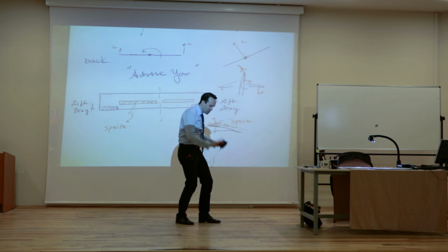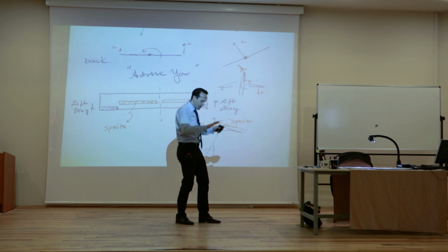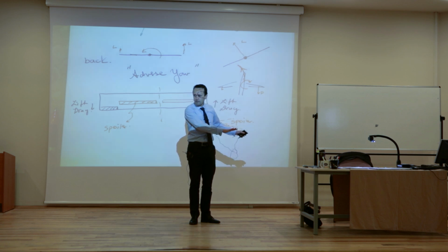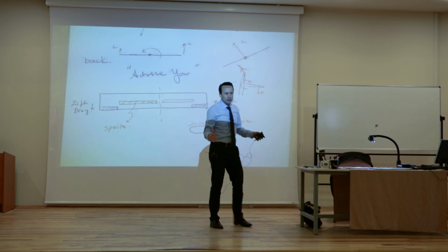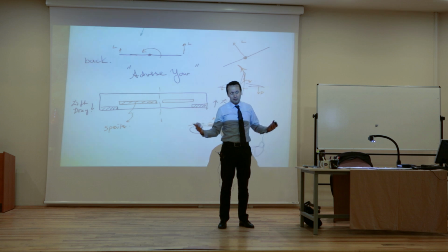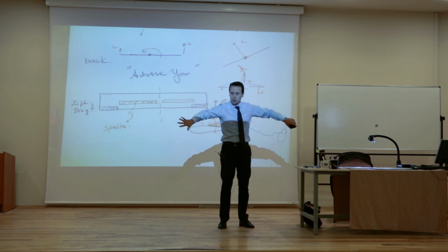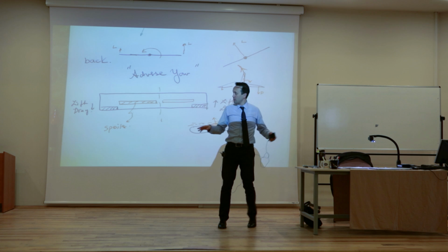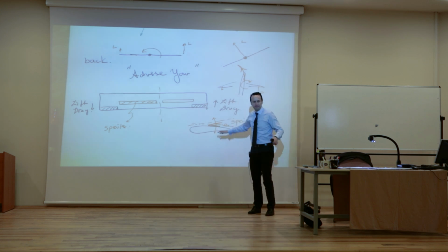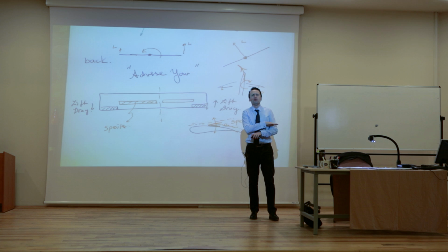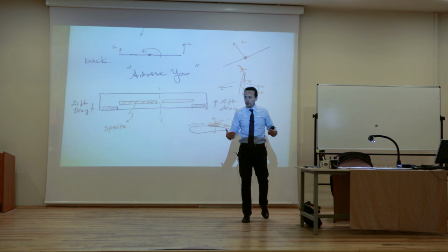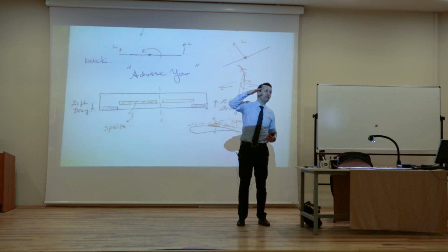So you've already put your feet on the ground. You just want to stay on the ground firmly and slow down the aircraft, okay? In that very moment, you will see the airplane, if it's a big airplane, has spoilers. It immediately opens the spoilers and leaves them there to really remove the lift. You want to have them open very quickly so that you remove all lift and also generate a lot of drag to slow down, but at the same time not to take off again.